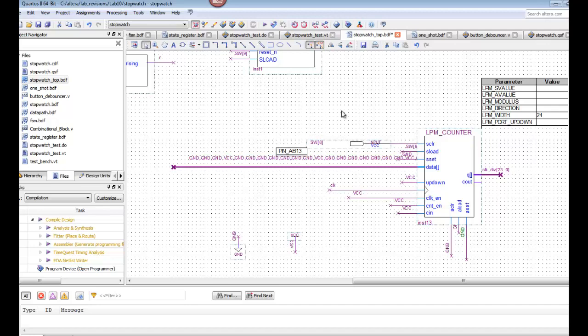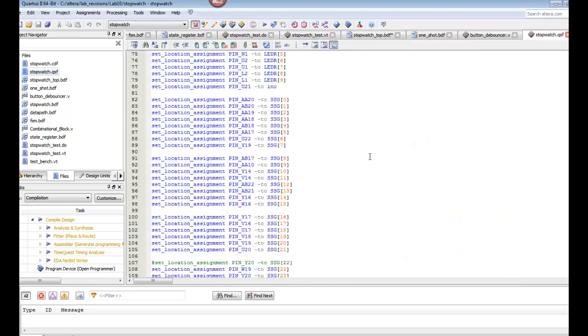If you want to see each of these bits, you can just have an output, which I happen to call SSG. That would show you each of the 24 bits, and you could see that they were divided by 2. As I mentioned in class, you cannot see the transitions changing very quickly. It's not until you get to about bit 16 that you can actually see a transition.